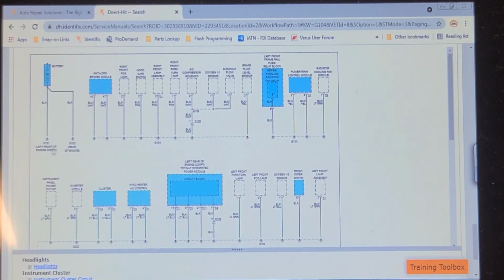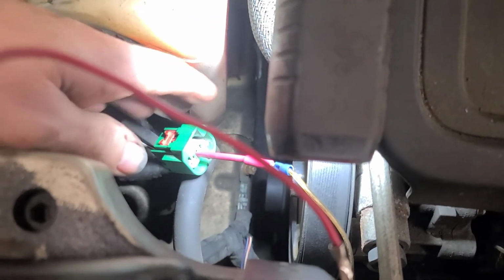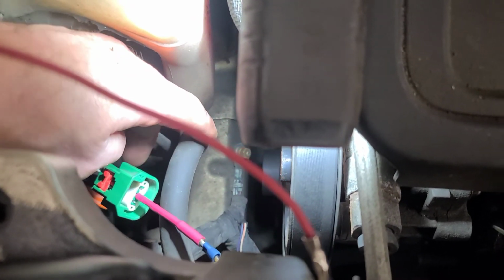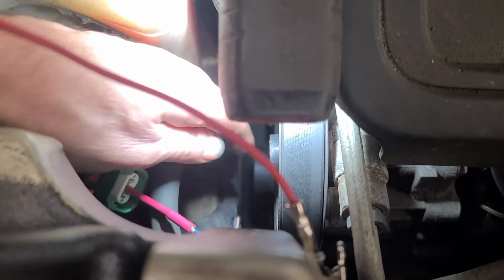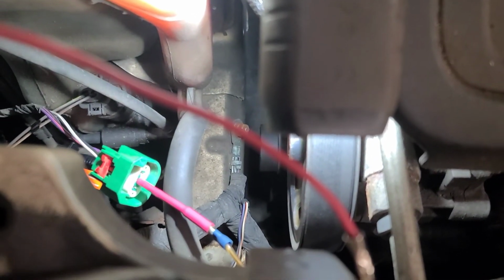So here it shows G101, left side of engine bay, 100 rear of engine, 104 you're on your own, 103 you're on your own. So I resorted to old school inspection, and I think I see it down there, way down there, and I've got the headlight connected. There's a lot of wires going to that ground.